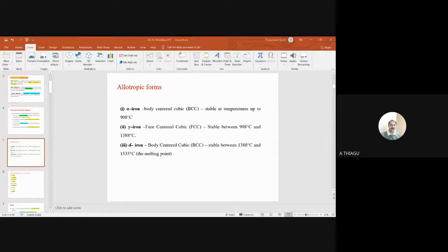So these properties depend upon the variables only. Okay, variables in the sense temperature and composition of the component. So comments on the Fe-Fe3C system. This is the particular information we have studied. Look at the very good information from the iron carbon diagram, the reactions. Already I suggested three important reactions in the phase diagram. One, peritectic, at high temperature. Eutectic, 1147 degrees centigrade. Eutectoid, 727 degrees centigrade. So this is easy to understand.